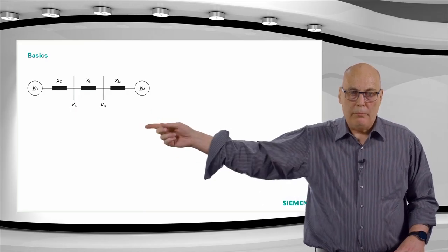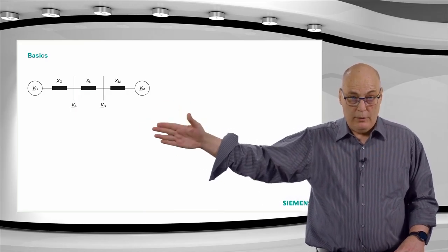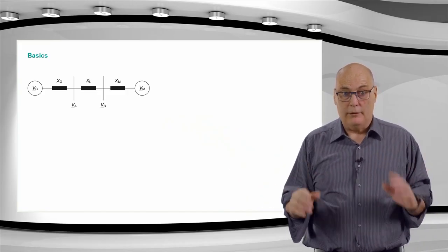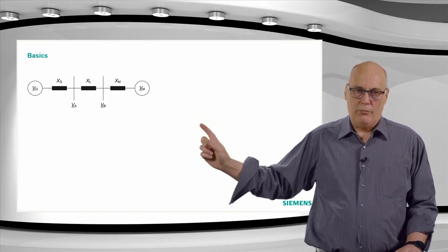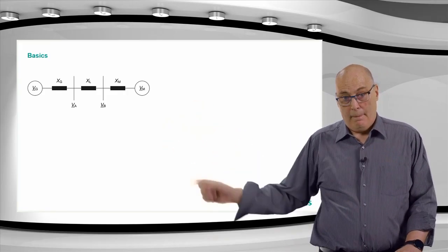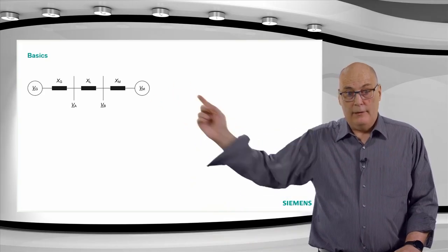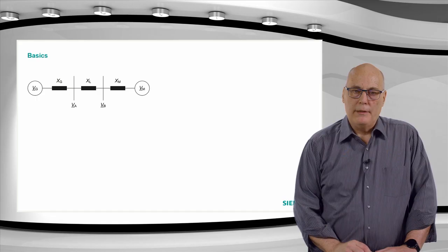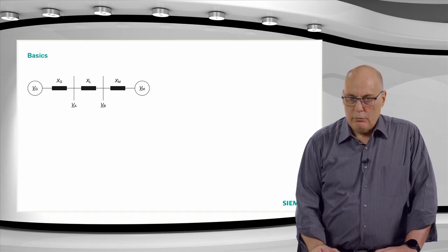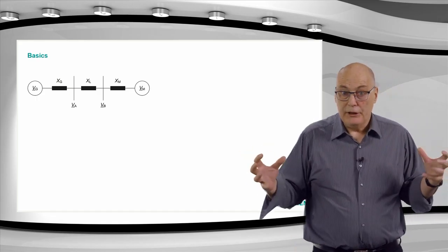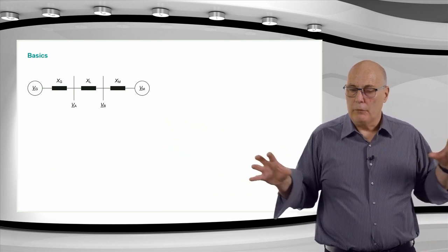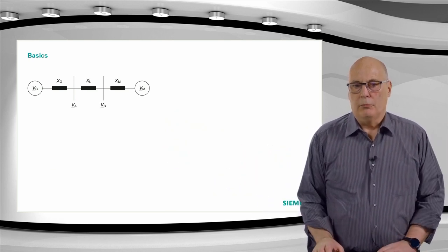So our relay would typically be at the VA, that would be the one bus bar on the left. VB is the bus bar on the right, not the A phase, B phase, sorry. So left-hand bus, right-hand bus, VA, VB. And then the load side impedance, the load impedance on that side. One can typically also consider this to be two sections of a transmission network, the generation side close to the generation and the VM close to the load side of a transmission network.